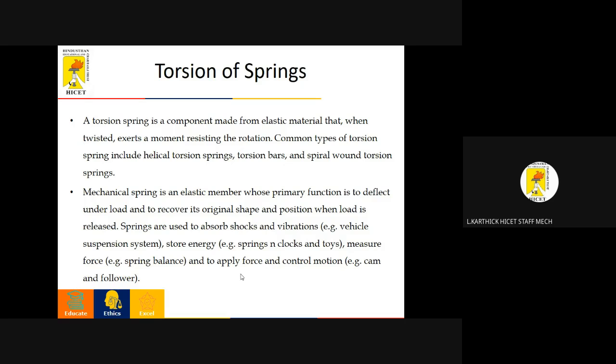For example, look at the spring in a clockwork: it is used to absorb energy when the clock is wound. This absorbed energy is gradually released at a slow, continuous rate as the clock runs. Another example is carriage springs or leaf springs in automobiles, which absorb road shocks by continuously absorbing energy due to shock through their deformation and then dissipating it by means of vibrating. In two-wheelers, the best example is the springs in the suspension system, which absorb the deformation.